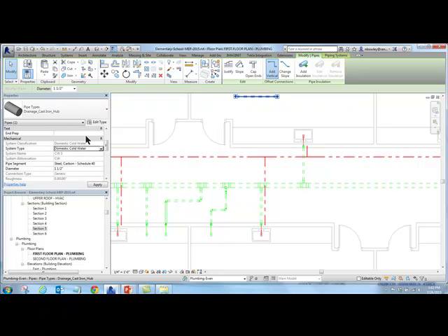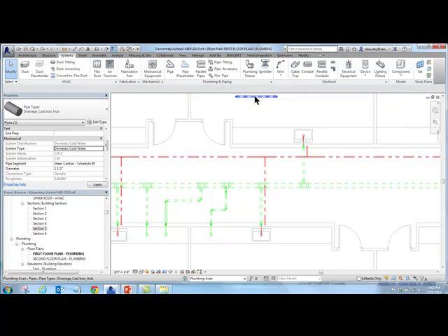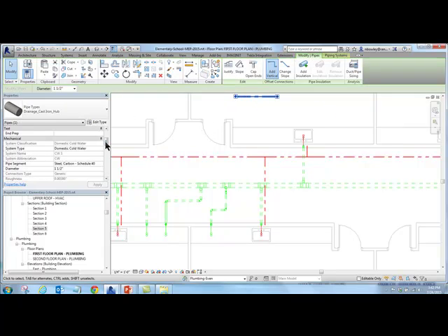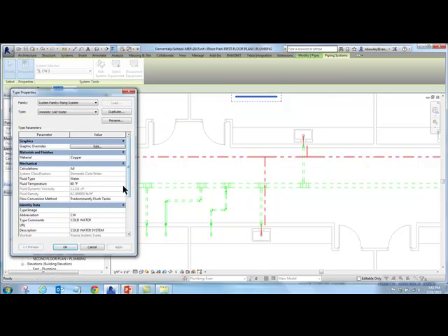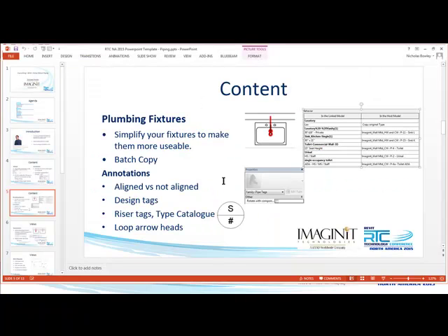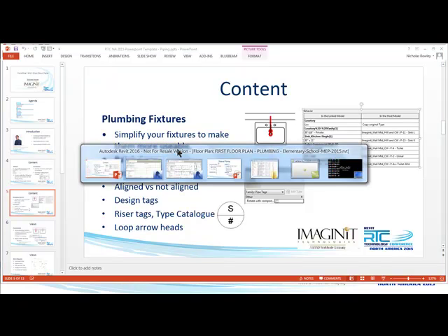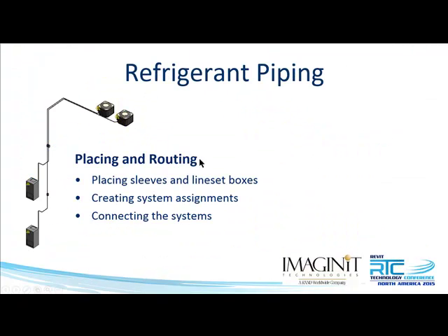Okay. So when you do domestic cold water, you're gonna want to have 2 plumbing systems, because when you edit the system type for domestic cold water, there's an option for flush tanks or flush valves. That changes how it calculates. So if you're doing cold water and it's not sizing correctly to match your table, which I have on the next slide, oops, we'll skip that.